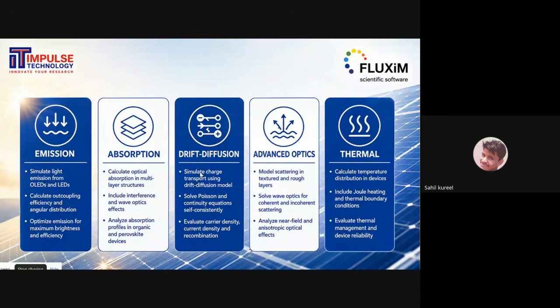And inside they have a large set like steady state, transient, AC, and intensity modulated photocurrent or voltage spectroscopy. Simulate charge transport using drift diffusion models in here. Solve Poisson and continuity equations self-consistently. Evaluate carrier density. Something that has been given, but when I open the SETFOS software, I will show how you can use it.